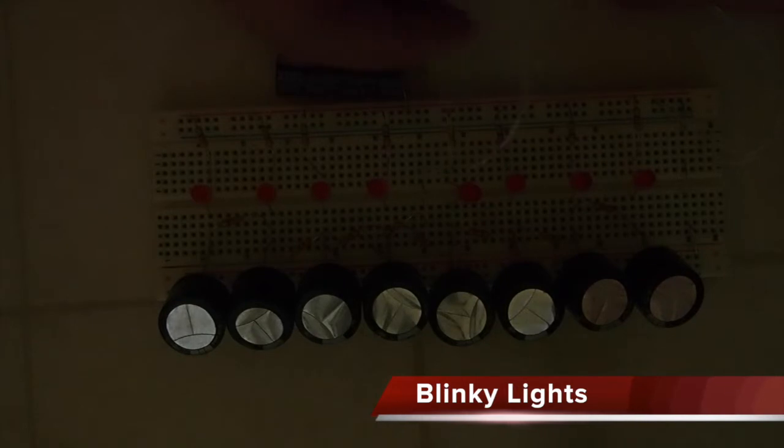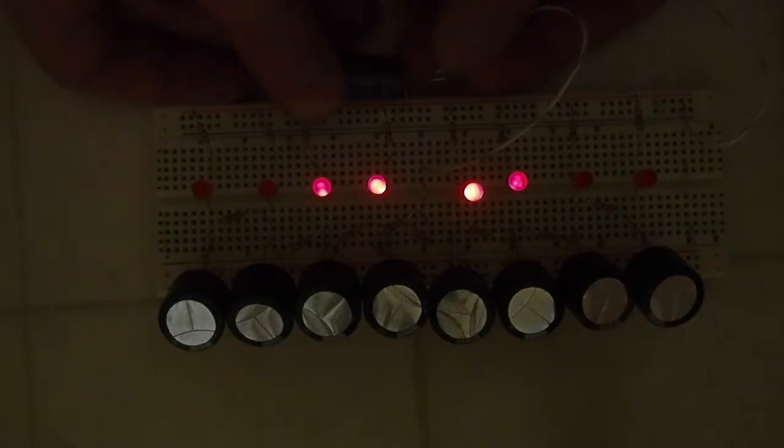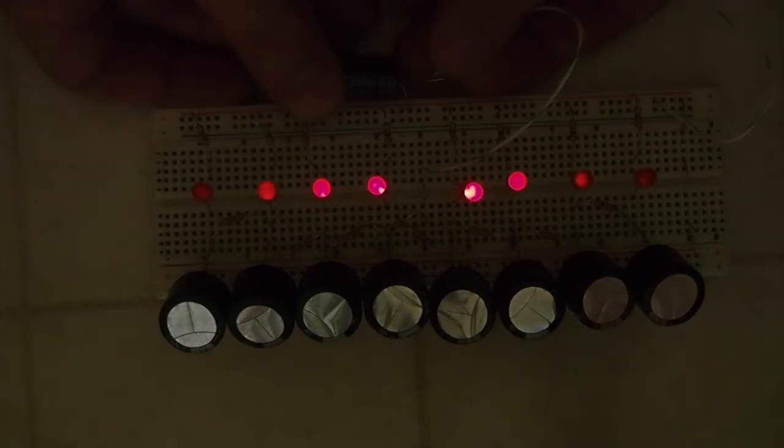Now on to the demonstration. I first discharge the system a little bit, and then hook up a 9-volt battery, let it charge. Now I'm doing this in a dark corner because these LEDs weren't getting very bright. Once I have the capacitor fully charged, I move the lead over, and I can see immediately the closest LEDs to the initial capacitor light up, and then slowly that light diffuses across the rest of the circuit.